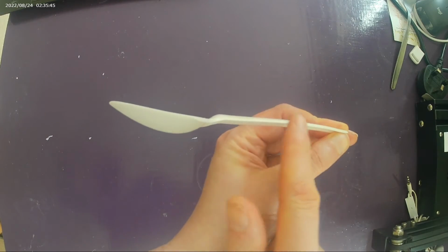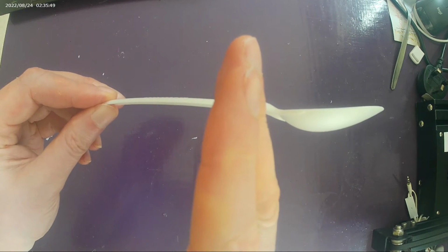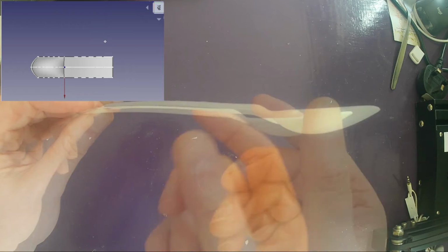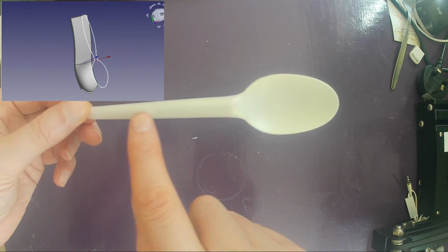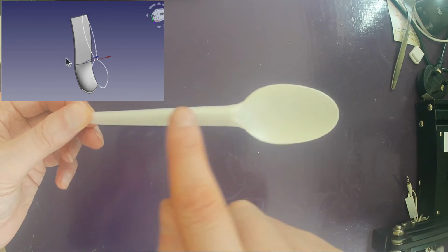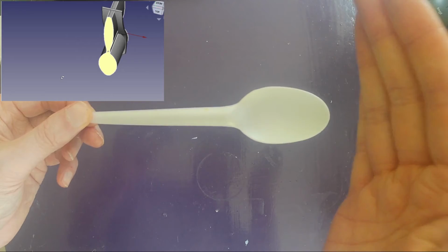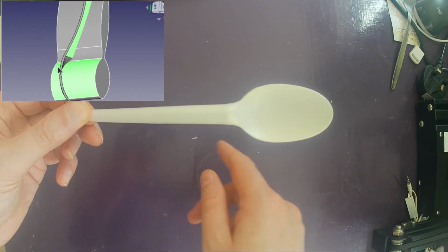So come around this side, it sits on this side. We then loft or sweep across those, going this way, and then we bring this around this side and then draw our shape, extrude that through the loft this way, and then create the intersection through both pieces.